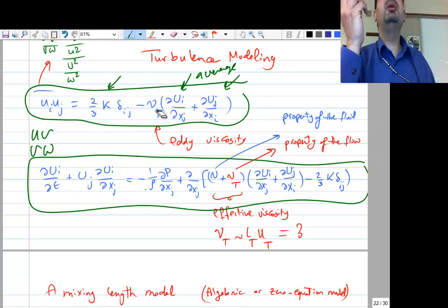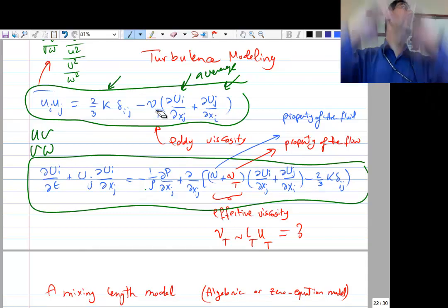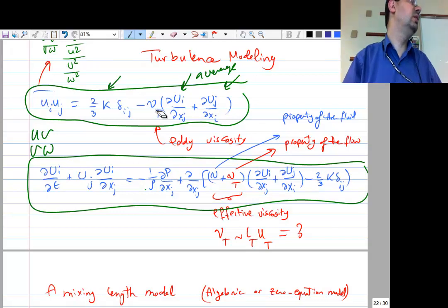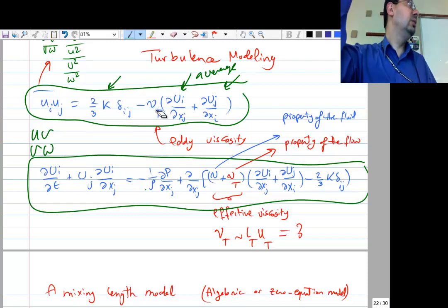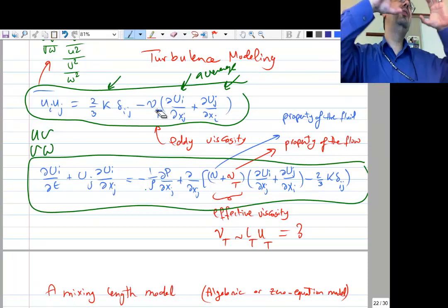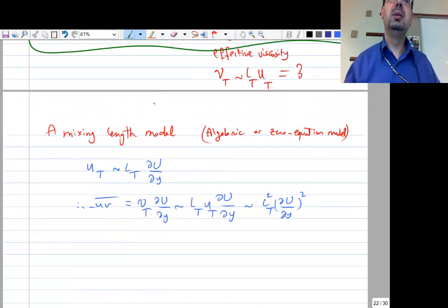So what you need to remember when your boss is telling you, well, can you run this model? We did this for turbulent flow over a pipe. We are just doing it for our rectangular duct. Tell us the flow rate. Just try it again with this new geometry. So you enter the new geometry, but what you need to worry about is the constant that did run for pipe may be different when you are simulating a duct. All right?